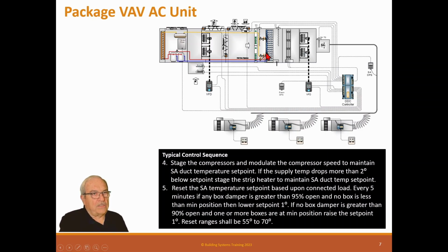So we can actually slow these compressors down, so again, probably not freeze up a coil. Not slug a compressor because we got too much refrigerant in the circuit. We can slow that down. This one also has a hot gas bypass, which means simply if this gets too cold and we start trying to freeze up a coil, it will take this hot gas and inject it right downstream of the expansion valve, heating it up to keep it from icing. So that means that we can run this in really cold temperature. We can air condition in cold temperature.